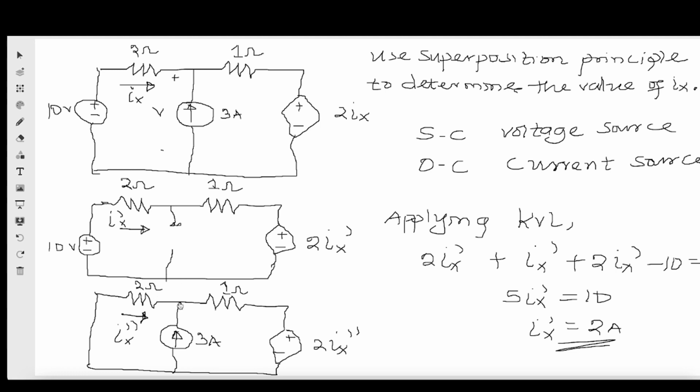So of course we have more than one node there. This is a node, right? This is a node, and this is another node. By nodal analysis, I'll make this my reference node. So this is the reference node. Then KCL at this joint. Right? So let me name this V.